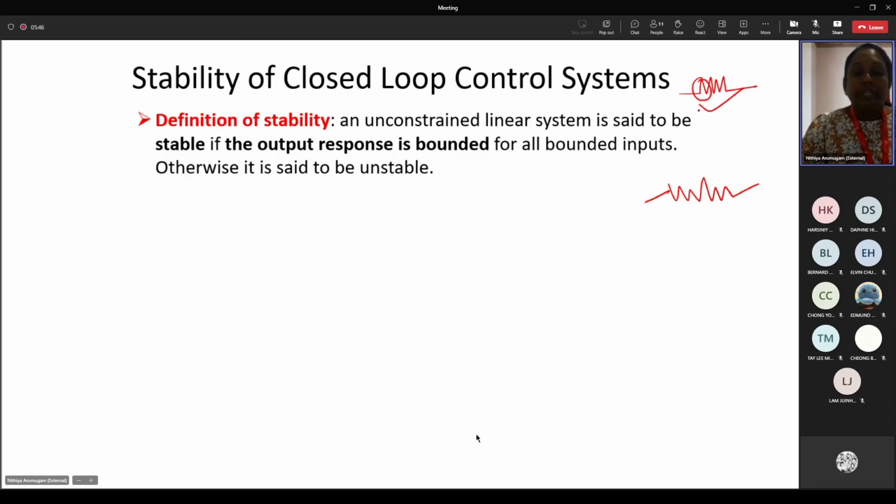All right. But under certain conditions, the oscillation may be undamped or can even have an amplitude that increases, meaning the fluctuation continues until a physical limit is reached. Until it reaches a certain limit, we call it the control valve being fully open or shut.